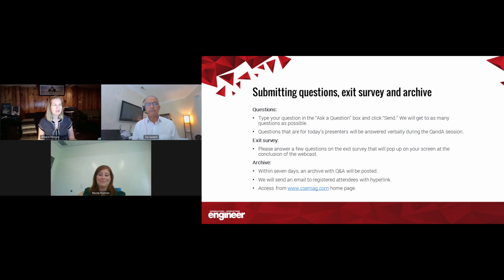Nicole, back to you. Are UPS battery banks arranged in multiple parallel strings to allow for failure? Usually they are not, but what we do a lot of times ask for is a battery monitoring system. That should give the owner a heads up before battery failure, to tell them something's going on with your batteries here. You need to replace one in your string. But usually you don't specify the system to have redundant batteries.